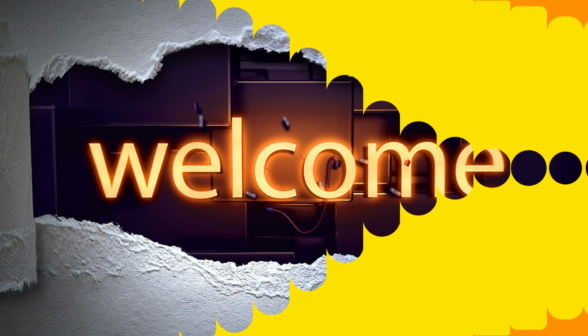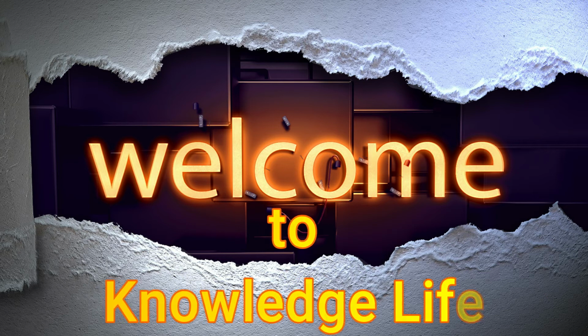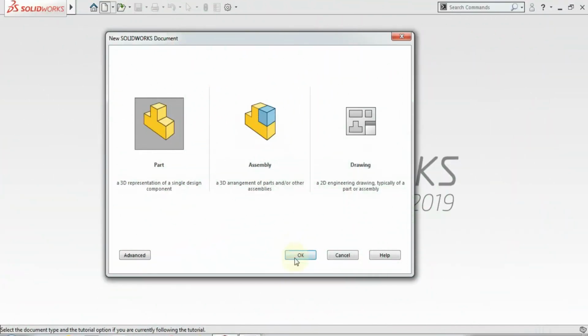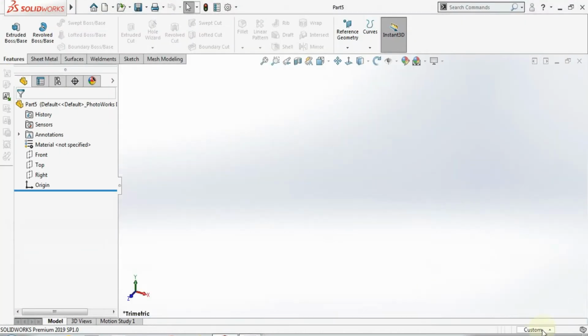Guys, today in this video I'll be talking about one of the most important features called extrude. So let's open a part, click on New, select Part. I'll choose here unit millimeter gram second. I'll choose here front plane.